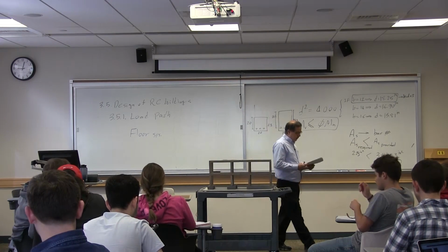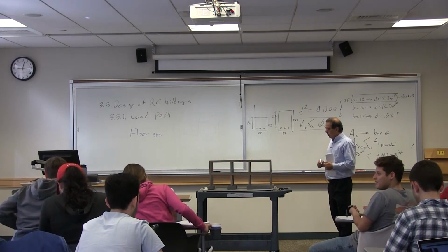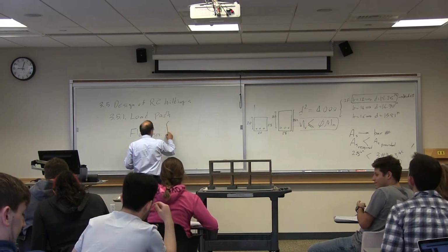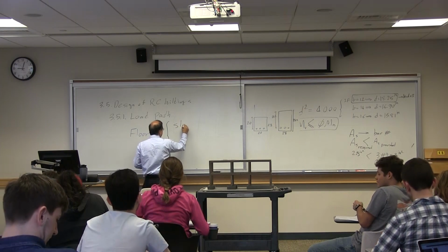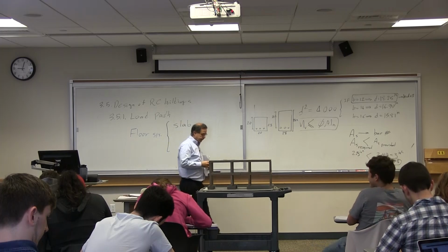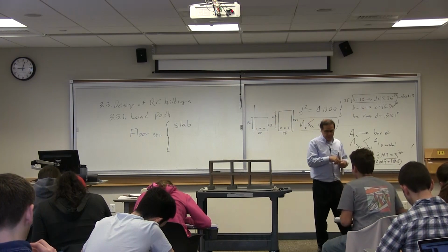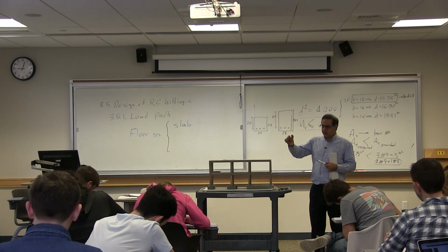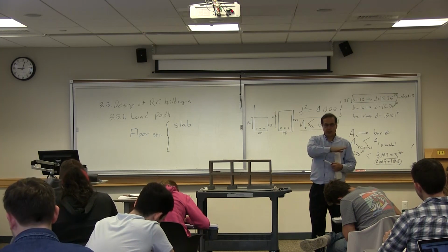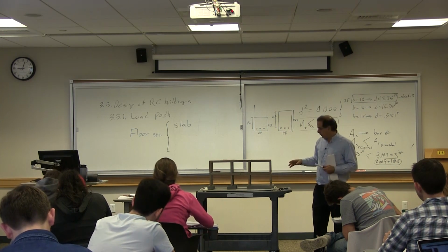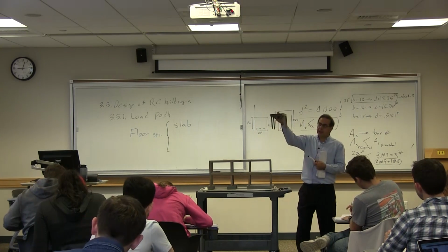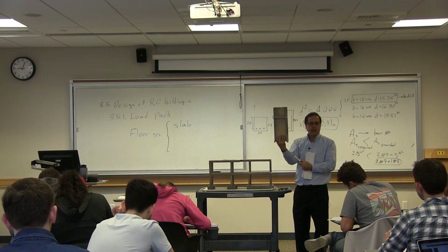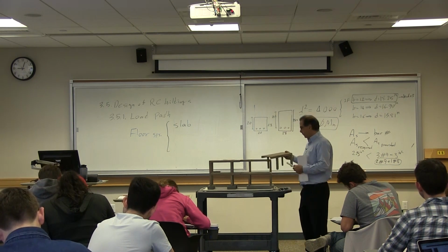So we were talking about floor systems. There are many types of floor systems. One of them is slab. Slab floor system is simply a constant, usually constant thickness concrete across the floor. For instance, if you look at this sideways, this thickness is constant and is everywhere the same. So this is called a slab.